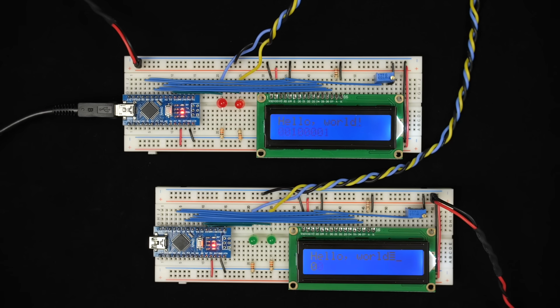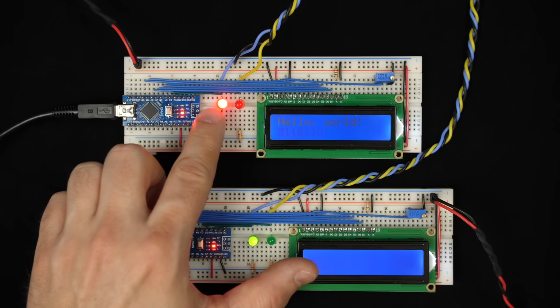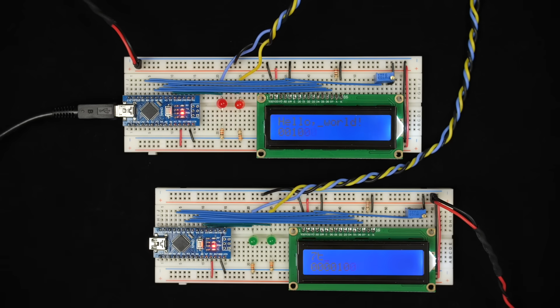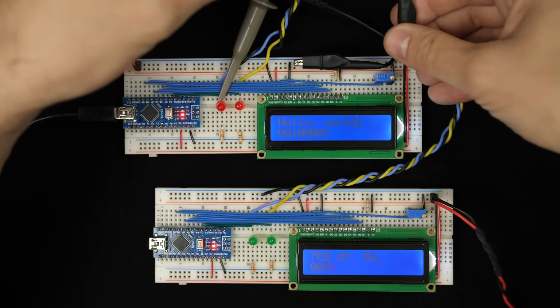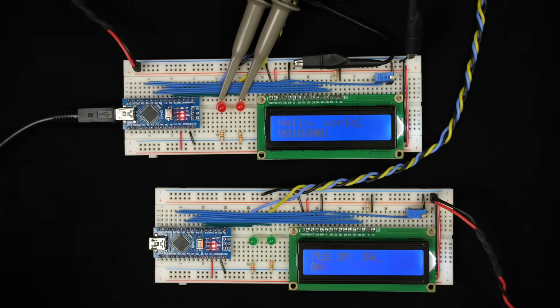And there it goes. We can see it looks like it's transmitting hello world, and now we can obviously see the clock is flashing. Every time this flashes, that indicates that we're sending a bit. And just so we're clear what that looks like, we can hook the scope up to that as well. So hook one probe up to our clock line, and then hook the other up to our data line.